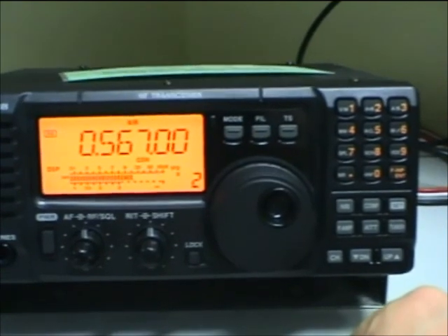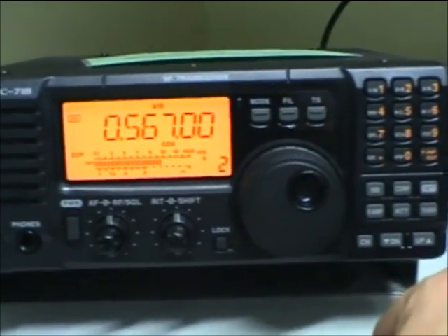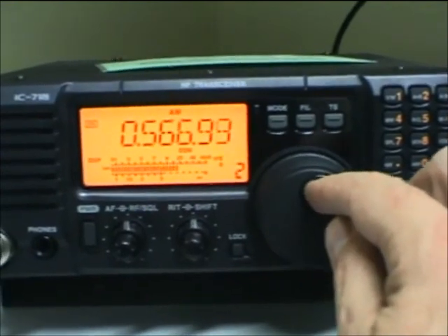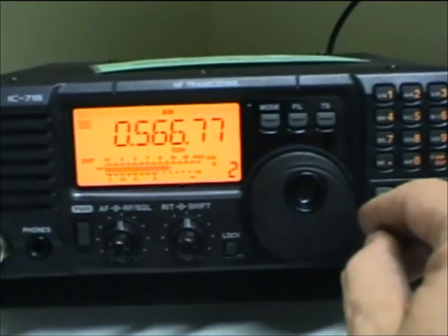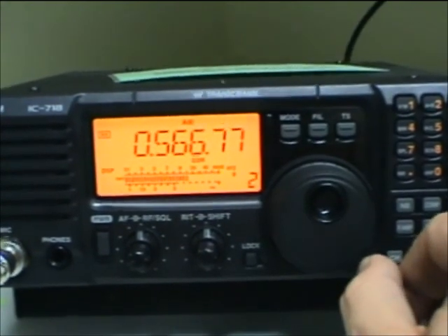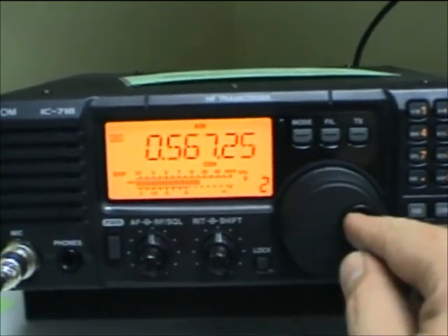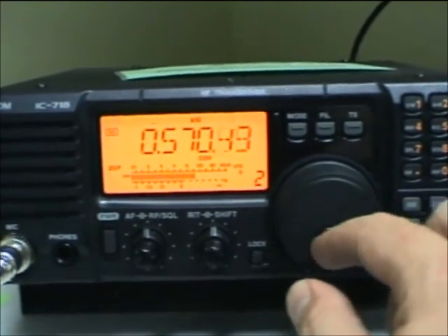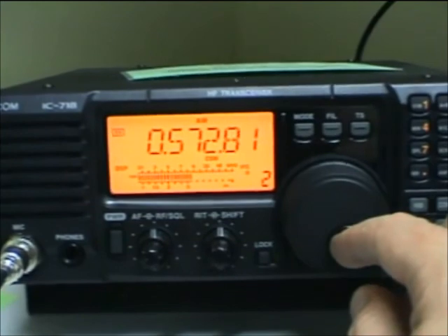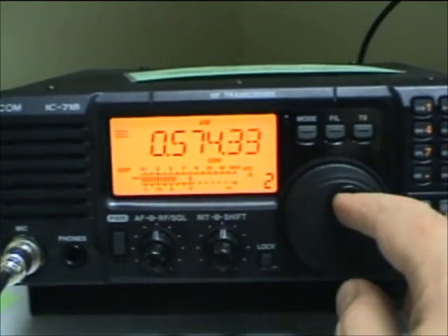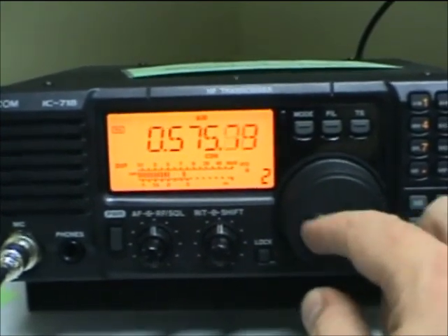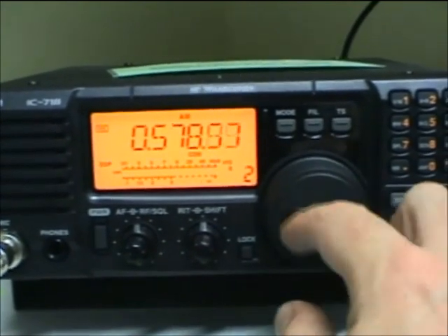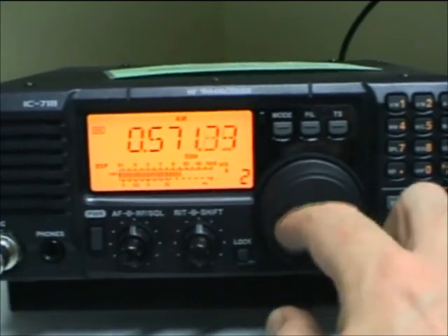There we go, there's New Zealand's national program, 567 kilohertz from over near Wellington. And as we tune off, there's no pitch change because the carrier is supplied, if you like, by the transmitting station, so it is not changing in frequency. The carrier comes along with the signal, but as you tune away, we start moving outside the IF filter pass band. The signal gets noisier and weaker, and eventually vanishes. It's not till we tune back to 567 that everything comes right.